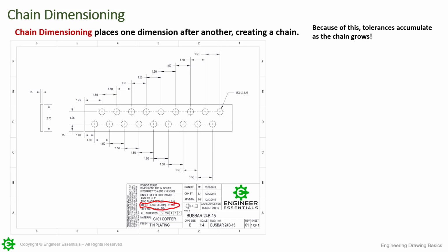So we've got 5 thousandths there. Because it is a 3 decimal place, we've got plus or minus .005. So the MMC of this is going to be .625. Remember, whether we're talking about GD&T or coordinate dimensioning, for these features, we still have our maximum material conditions and our least material conditions, or upper limits, lower limits. So we have these 18 holes. Based off of the dimensions up here at the top, we're going to use this one right here. So look at this hole.